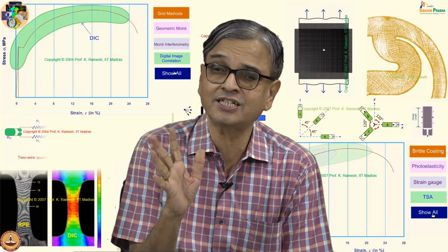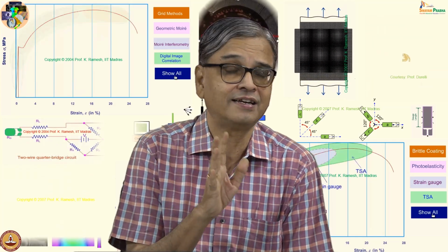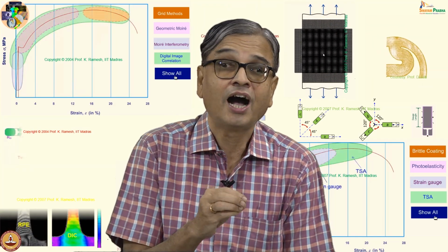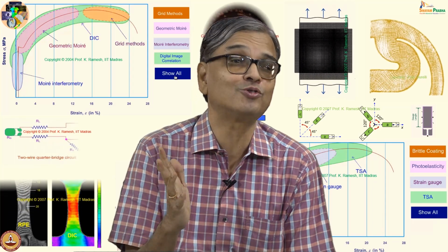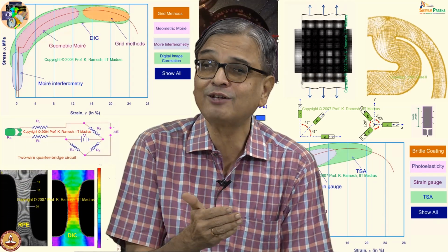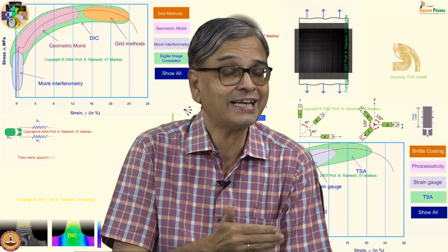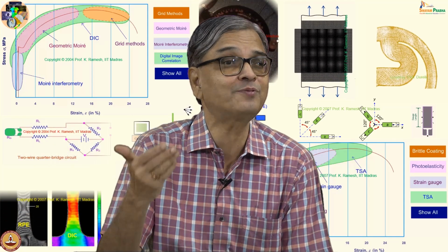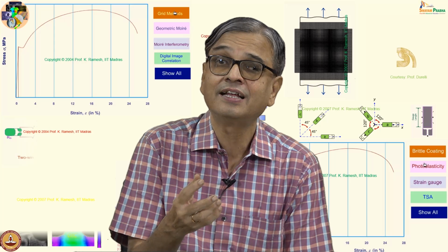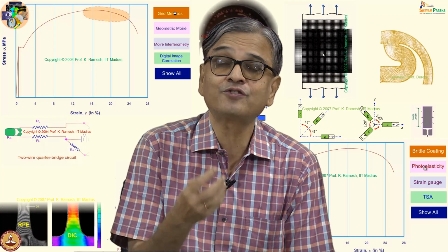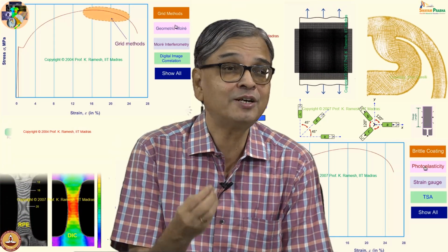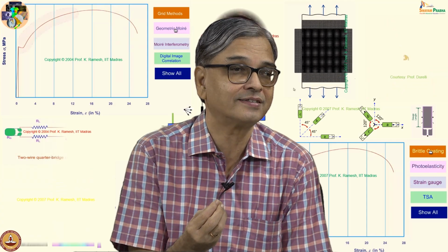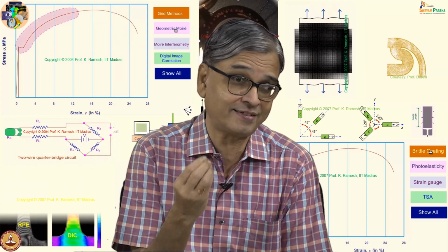See, one of the challenges when they discovered strain gauge was how to measure microvolts, because I am going to have micro strain. So the electrical change also will be in very small quantity. So people needed amplification circuits for them to have measurement of this very small voltages. You have to recognize that is 10 power minus 6.